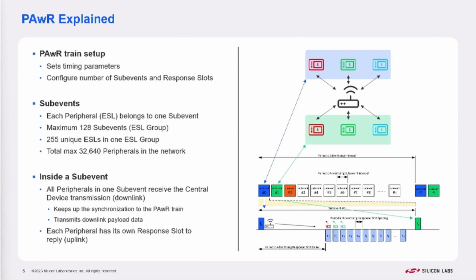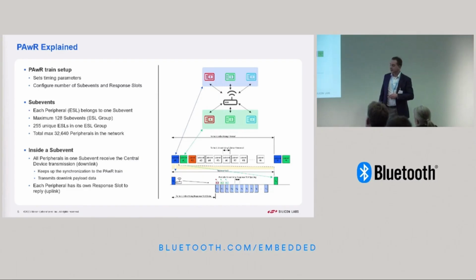Obviously, that message can also contain data, and then the response feature kicks in. And then there is the Bluetooth ESL profile and service. There's a standardized way for how these responses are timed and in what order. Now each individual device on the network can respond back to the gateway. So now you have a bi-directional network, which is really super low power and scalable.